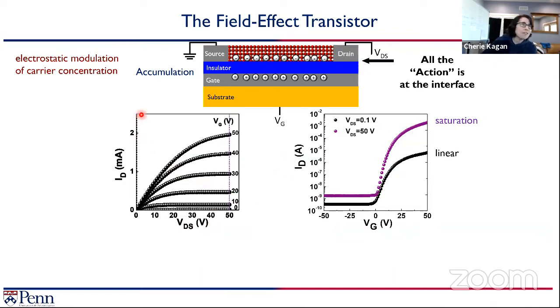So if you look here, I have this little dashed line down here on the left. That's at very low voltages, like 1/10 of a volt. It's very hard to see because they're at a much lower magnitude than the absolute scale here. So I'll highlight that this region here is known as the saturation regime. I'll explain that in just a second, but you can see that below 0 volts we have very little current, and as we come up above 0 volts on the gate, you start to see the current get bigger and bigger, which is what you see here in the purple plot.